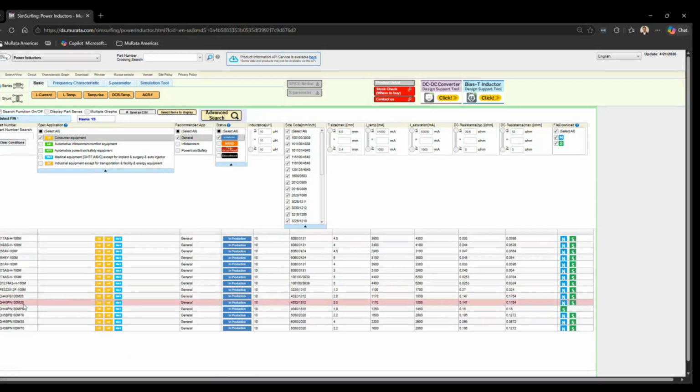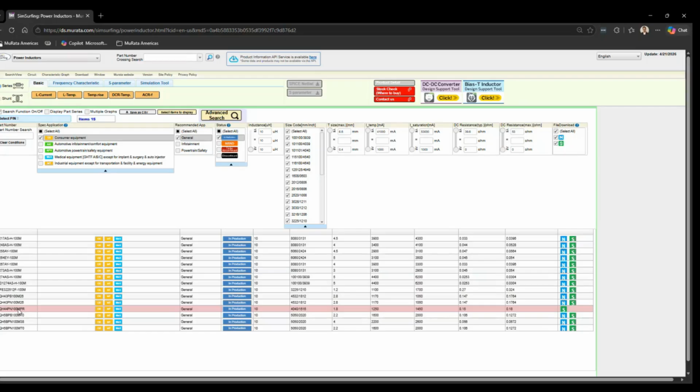And then here you have different options. Just like with the RF inductors, you do have different builds with the power inductor. The core could be a ferrite material, which is used to give you higher bulk inductance, but it also exhibits higher saturation with applied current, so that effective inductance will fall off a cliff, just like with DC biasing effects on a capacitor.